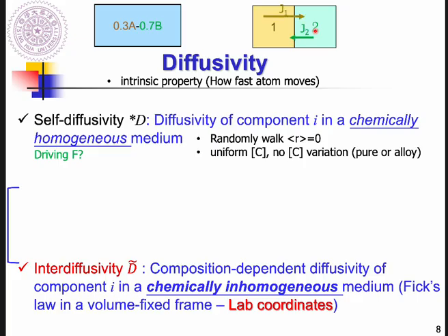If J1 is larger than J2, then we spontaneously have a vacancy flux moving to the left-hand side to allow the net flux to equal 0. So, a quick review: where will vacancies be formed? On the left-hand side. And where will the interface move to? It will move to the left-hand side because J1 is larger than J2, right? Okay, this is what happened.